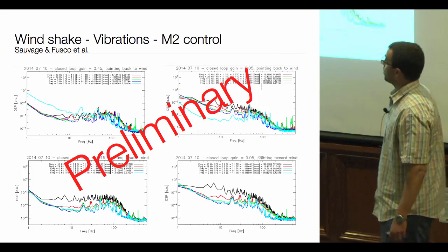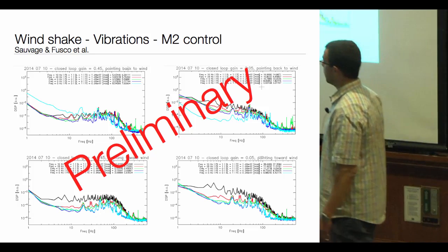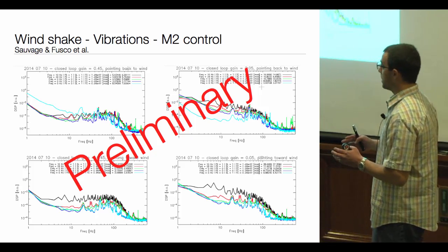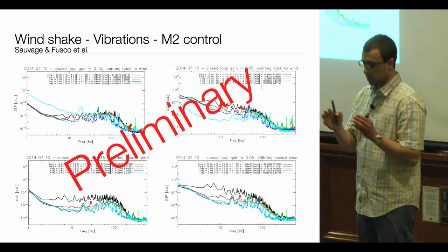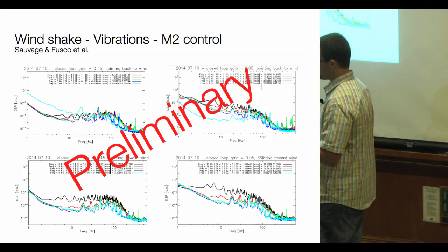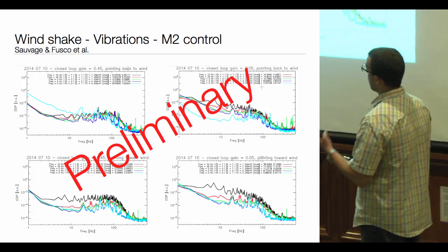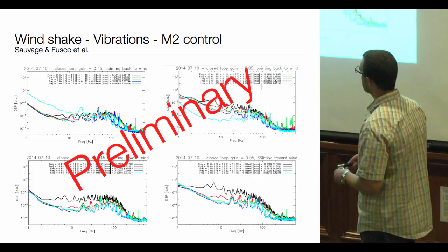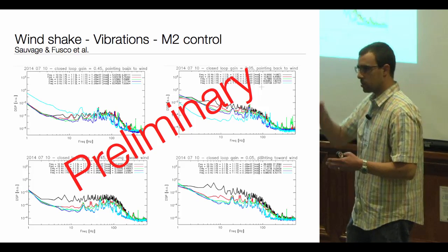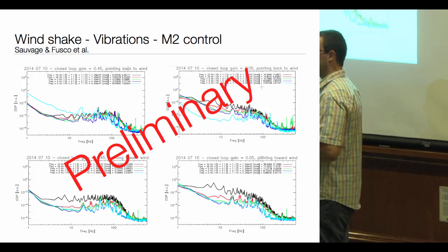So this is probably the most important one. This is the interaction with the telescope. So during the first commissioning of SPHERE, we noticed that the jitter residuals were 3 times as high as expected. So the consequence on the Strehl ratio was a loss of 10 to 15%, which would affect performance, especially at small inner working angle. And we found just a couple of weeks ago, we confirmed, that the origin of this shaking jitter was actually due to the servo loop of the secondary mirror of the VLT. So the solution is simply to turn it off.